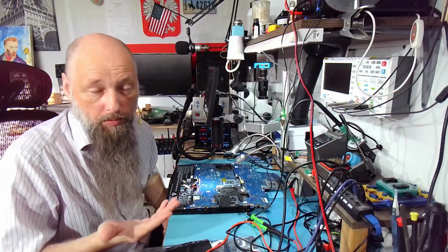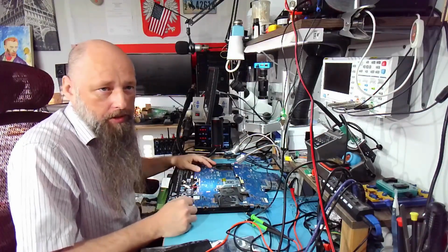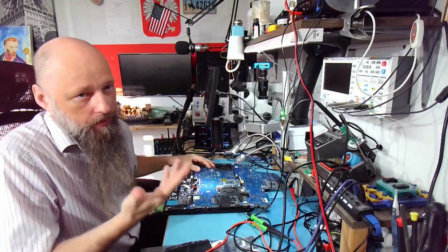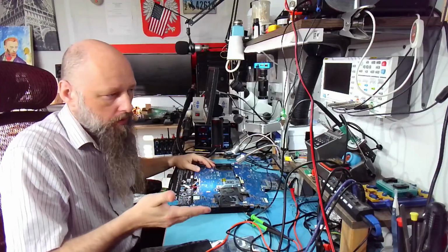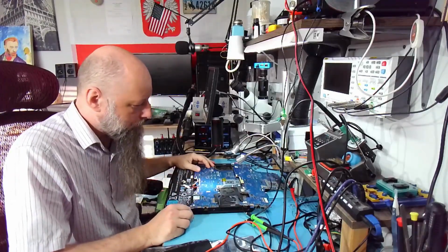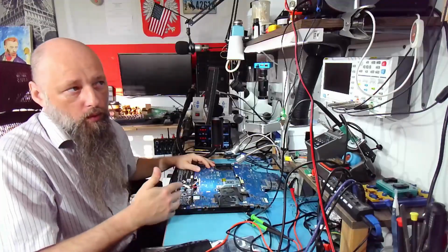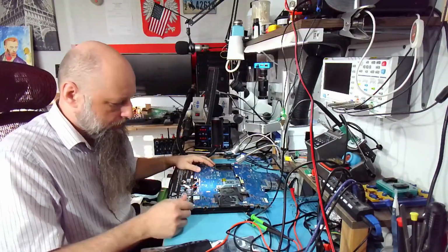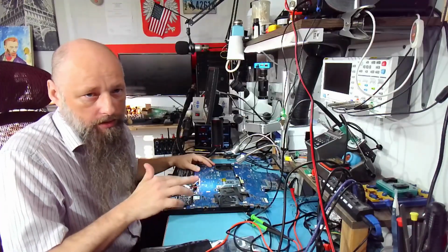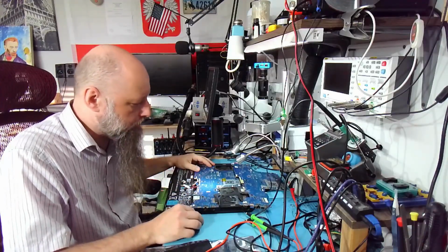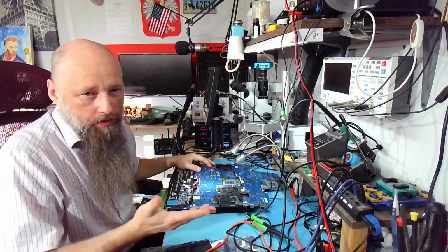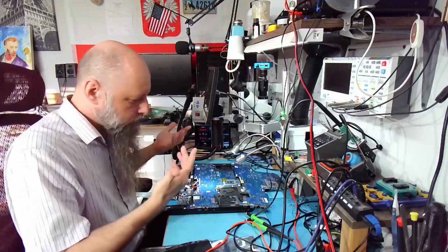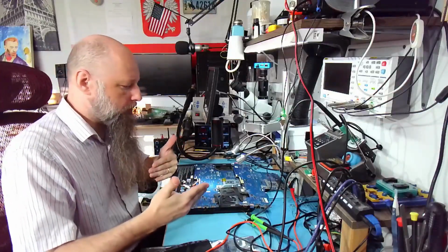So it doesn't enumerate. The no enumeration problem usually is a result of either the GPU completely failing, right? Shorted core, exploded core, or power failure. Or it also could be a CPU issue, it could be a PCH issue, it could be, actually more likely, an EC or SIO issue. The GPU might not turn on because of a power failure, or the EC is not turning it on. The voltage is not enabled.